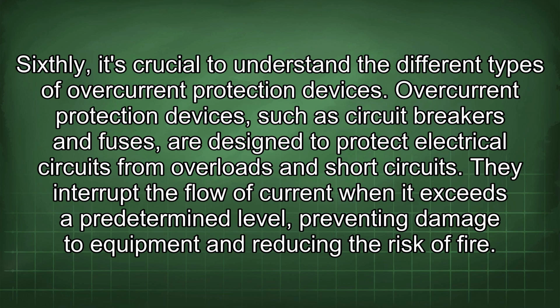Sixthly, it's crucial to understand the different types of overcurrent protection devices. Overcurrent protection devices, such as circuit breakers and fuses, are designed to protect electrical circuits from overloads and short circuits. They interrupt the flow of current when it exceeds a predetermined level, preventing damage to equipment and reducing the risk of fire.